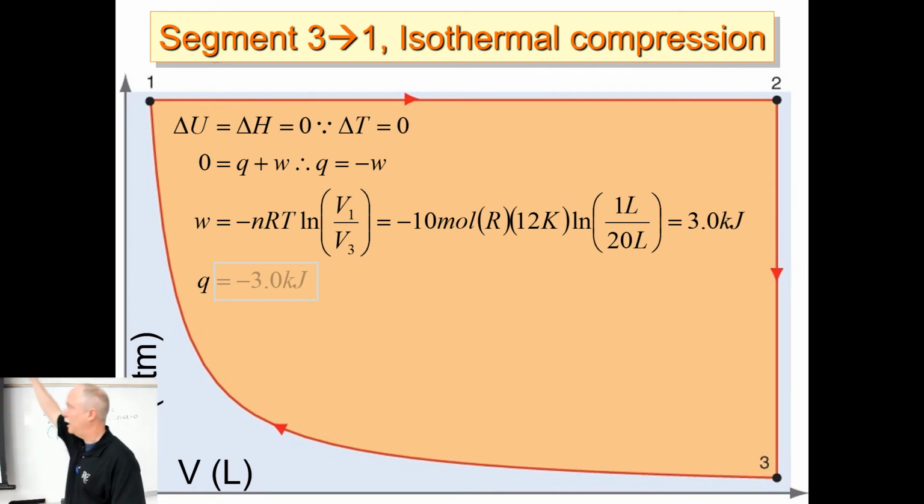In this previous leg, we dropped the pressure and dropped the temperature, and our delta H and delta U were negative. That's telling us the system lost energy. Well, yeah, how are you going to get the temperature to drop? You're going to suck energy out of the system, and the temperature's going to drop. Here, we're compressing our system. We're compressing 10 moles of helium, and the work term is positive, right? We're doing work on our system. We're resetting it by pressing it into a smaller space. So it should have a positive work value when we're doing compression.